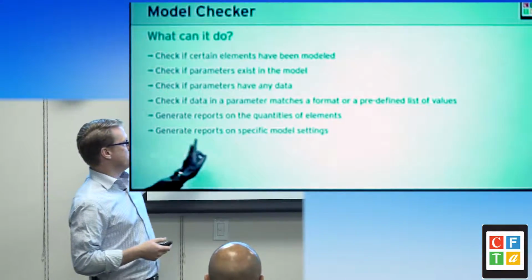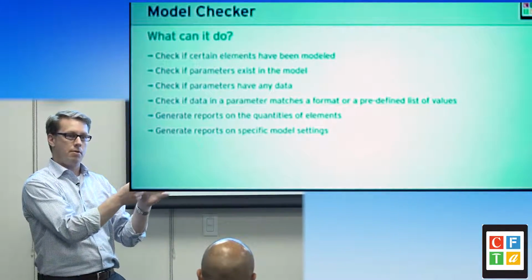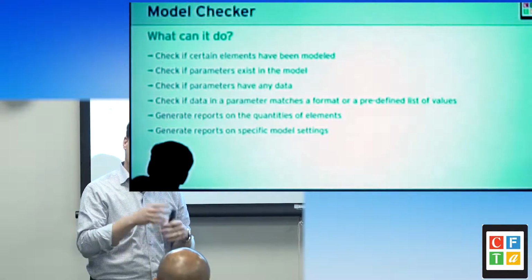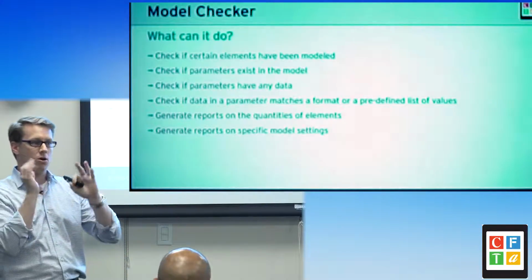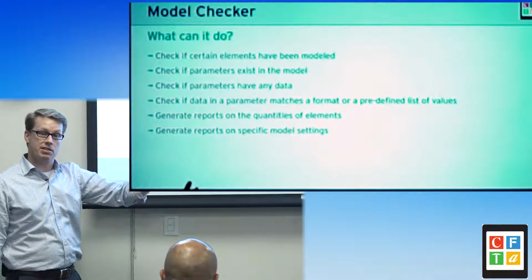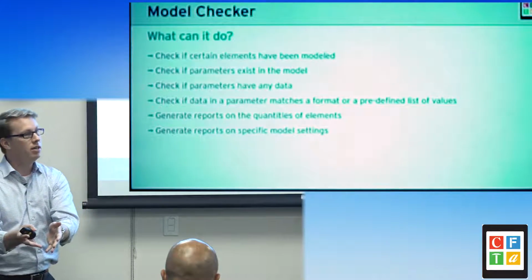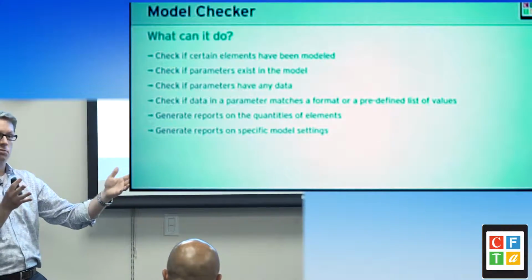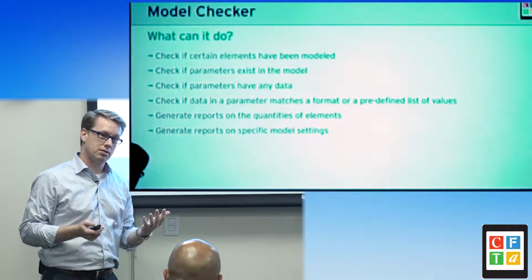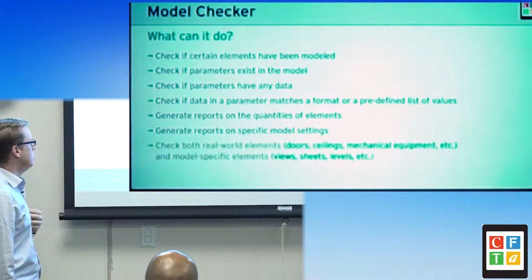It can generate reports on specific model settings, right? So it's great that you have a model with everything modeled right, but that actual model file needs to be set up a certain way based on your requirements. So it can look at that and make sure they set it up a certain way and they didn't add all kinds of extra stuff. Or, one thing we see all the time has to do with phasing. So you know the phase something is created and the phase something is destroyed, essentially, and any phases in between that. And so did they put it on the right phase for that project, which may just be existing now that it's an as-built model. So it can check all of that.